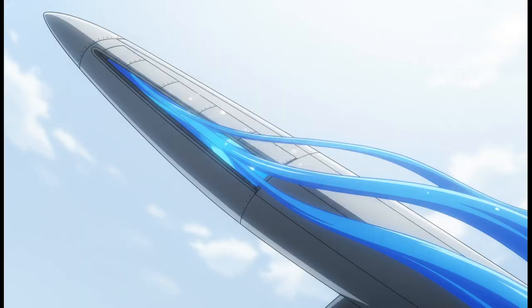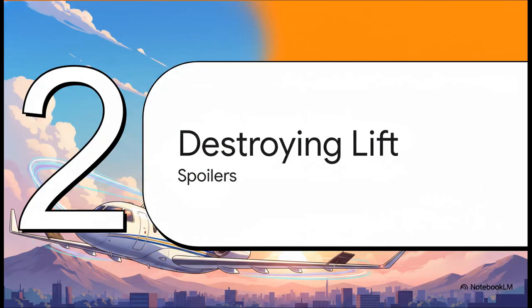All right, moving to the leading edge. Fixed slots direct airflow to the upper wing surface to delay separation at high angles of attack. Movable slats do the exact same thing, but slide on tracks. They deploy either automatically due to aerodynamic pressure or manually. Leading edge flaps physically extend to increase camber, and leading edge cuffs extend the leading edge down and forward, essentially wrapping the airflow so it sticks better at those high angles. The big picture for your exam: all these devices let the aircraft reach a significantly higher angle of attack before a stall happens. Moving right along to the descent phase.